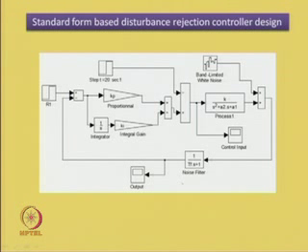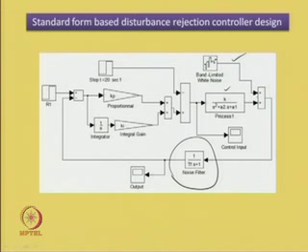Where is that controller in this loop? We have got a controller placed in the feedback path. So, the controller now is known as a noise filter. The primary job of this noise filter is to filter out the measurement noise. This is the process. The measurement noise can be shown in this form: when some sensor is put over here, the noise introduced by the sensor is shown by the band limited white noise injected at this point.